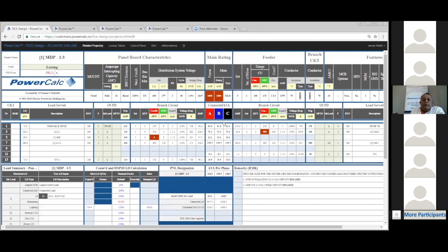30 degrees Celsius. So yeah, I can apply the rule of thumb. I've done it 20 times or whatever, so the result is going to be the same. Not realizing that now the ambient temperature will actually affect the capacity, or the ampacity, of the conductors. So you didn't actually run your calculations adequately and per the NEC, you're either going to be undersizing the conductor or oversizing the conductor.